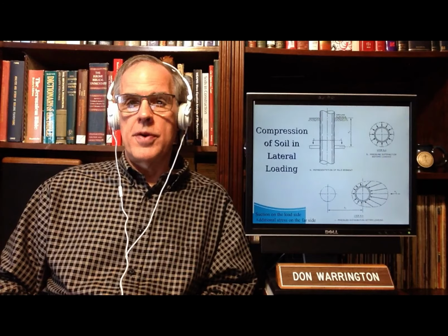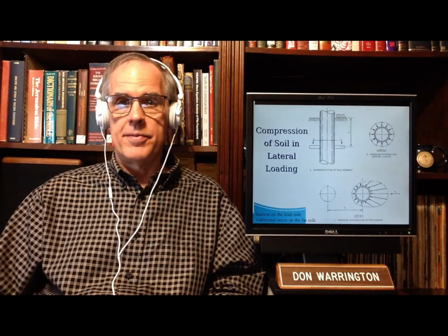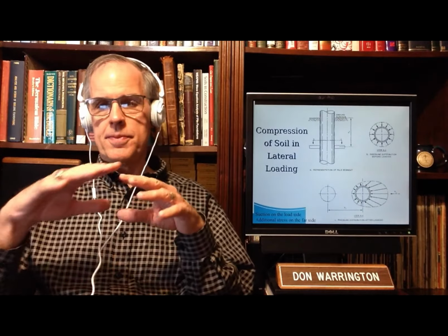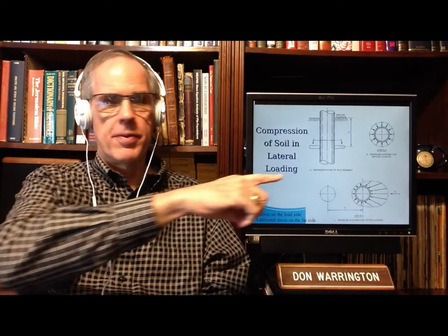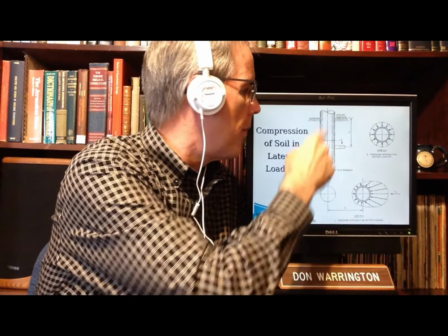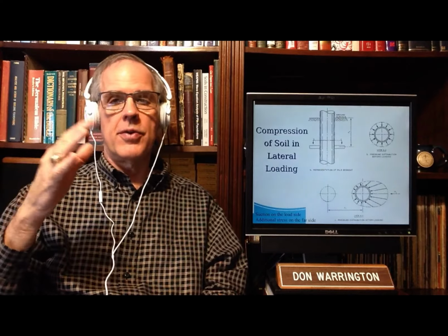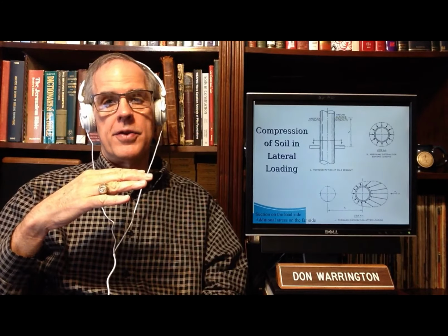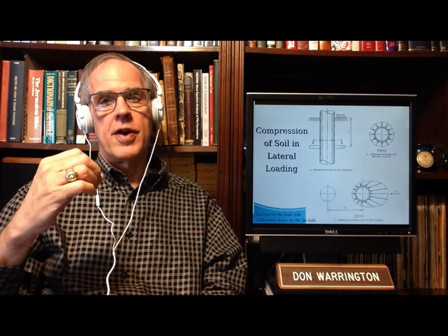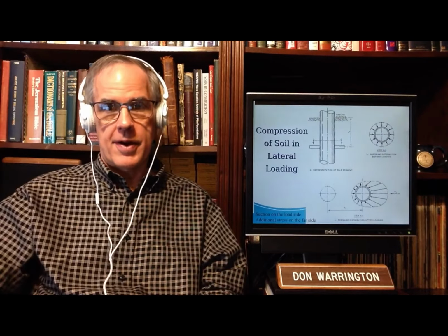Part of the nonlinearity, of course, is the soil. Soils are always nonlinear. Some of it, though, is due to the nature of the soil. If you take a slice of soil at any point along here, and by the way, whether you use a rigid method or a flexible method for the pile, no matter which one you pick, the deflection of the soil from the rest position is always changing as you go down the pile.